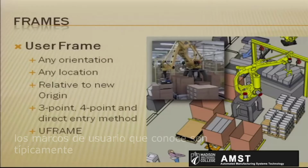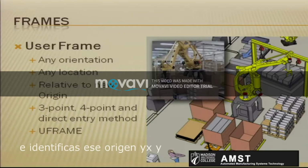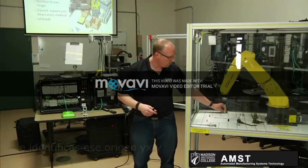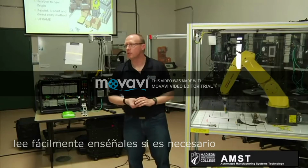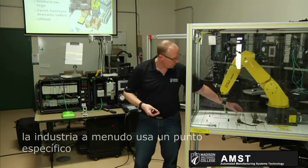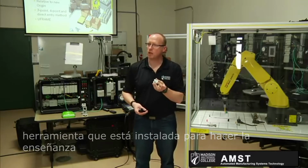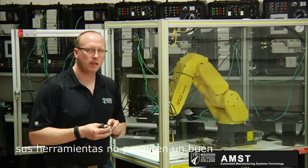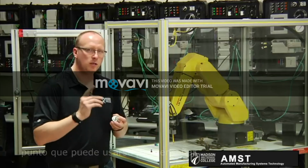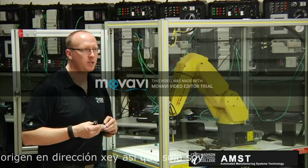The user frames are typically used if you have parts that are fixtured and you identify those origin and X and Y direction on your fixture, so you can easily reteach them if needed. Industry often uses a specific point tool that's installed to make teaching the user frame easy, because sometimes your tooling does not allow for a good point that can be used to teach the origin and X and Y direction.